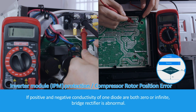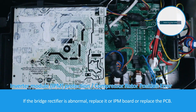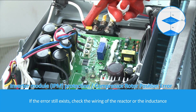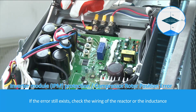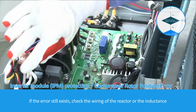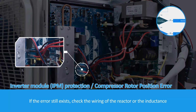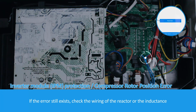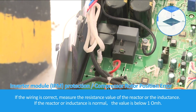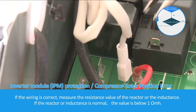If the bridge rectifier is abnormal, replace it or the IPM board or main PCB. If the error still exists, check the wiring of the reactor or the inductance. If the wiring is correct, measure the resistance value of the reactor or the inductance.